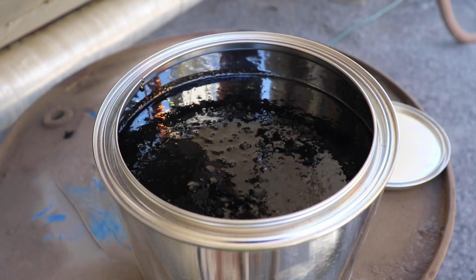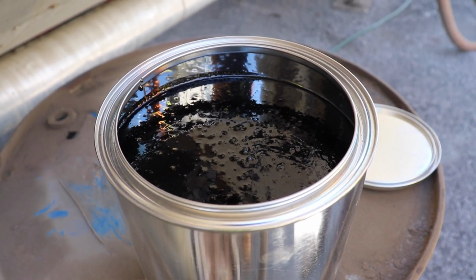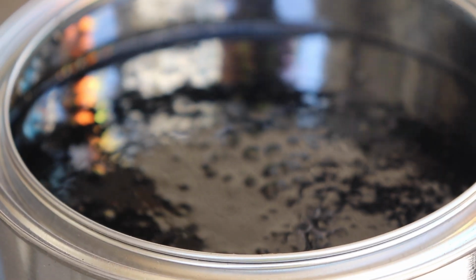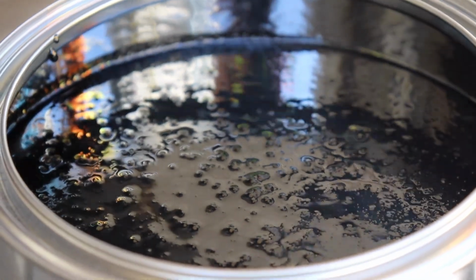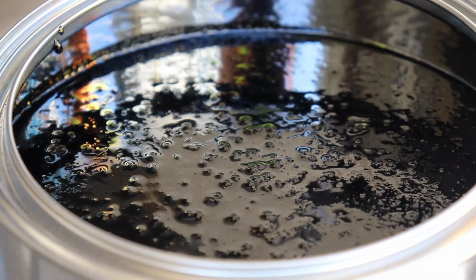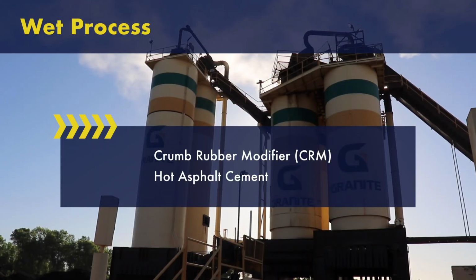The definition of asphalt rubber has been identified by several ASTM standards: ASTM D8, ASTM D6114. Rubber modification of asphalt concrete mixes can be accomplished using two distinct wet processes: the high viscosity agitation method and the low viscosity no agitation method, commonly referred to as a terminal blend. The wet process requires thoroughly mixing crumb rubber modifier, known as CRM, into asphalt cement. The resulting blend must be held at an elevated temperature for a designated period of time to permit an interaction between the CRM and the asphalt cement. This blending is performed at the hot plant.